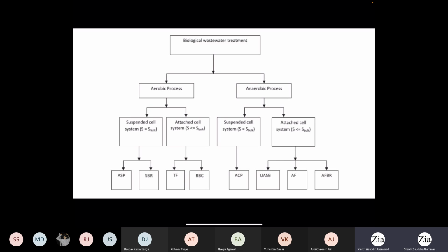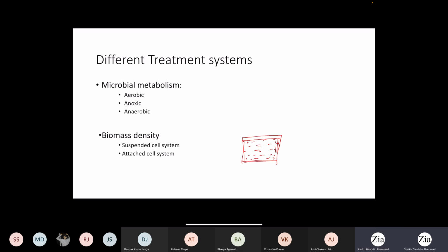If you agitate the system to keep the solid particles suspended, you also need to make sure that the settling velocity of the particles is not higher than the velocity you are maintaining in the reactor to suspend them. It has a certain capacity, because beyond that, if you keep adding solid, after a certain period of time the solid will get precipitated. So the suspended system has a limitation on the amount of solid in a given volume.